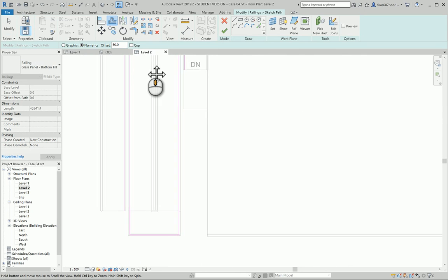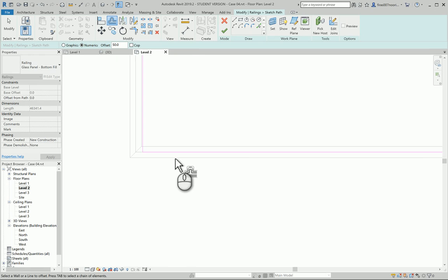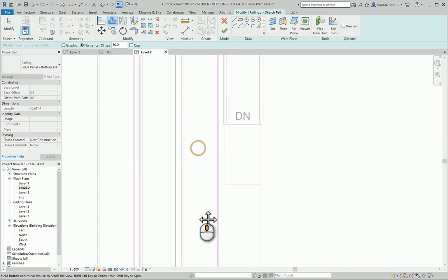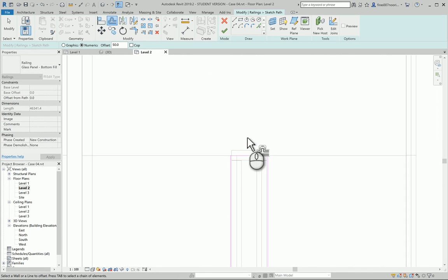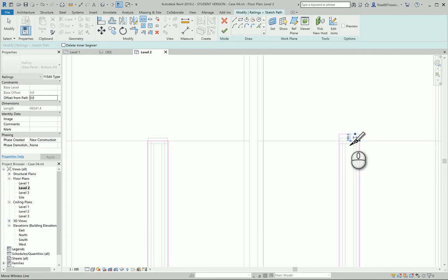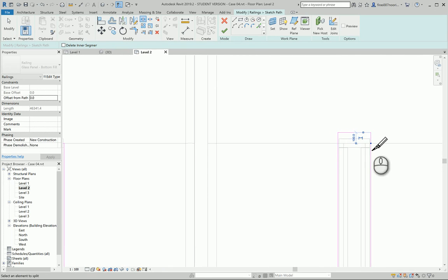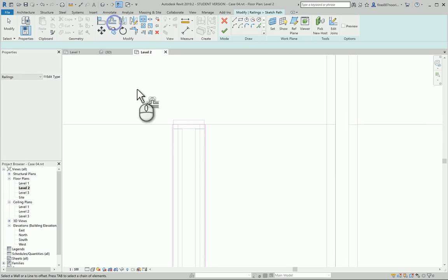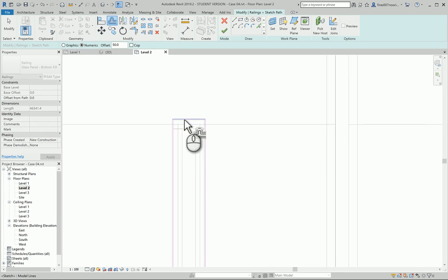That sounds good. So this one also to the top, and here probably you might need to push that, I don't know, twice. And while we are here, make sure to split on the point to allow this to be straight, straight, straight, and then inclined, inclined. Otherwise it's gonna be a big mess, trust me. Don't forget to split it. That's one, that's two. Then split this poor thing at the edge of the slab. Finish.